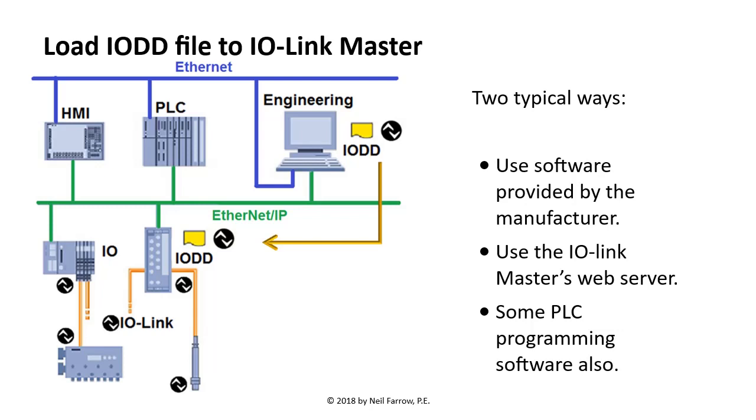There's a couple of ways to load the IODD file depending on which master you have and which PLC. You can sometimes use software provided by the master manufacturer, and some PLC programming packages could also load the IODD file when you configure the whole network.